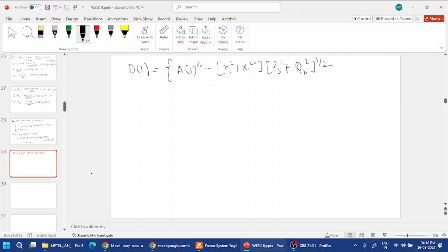If we put the values in this formula, it's just a simple formula, and we calculate these in a load flow analysis of a radial distribution system. Based on that, it will come out to be 0.4817. We just have to put in the values we just calculated.